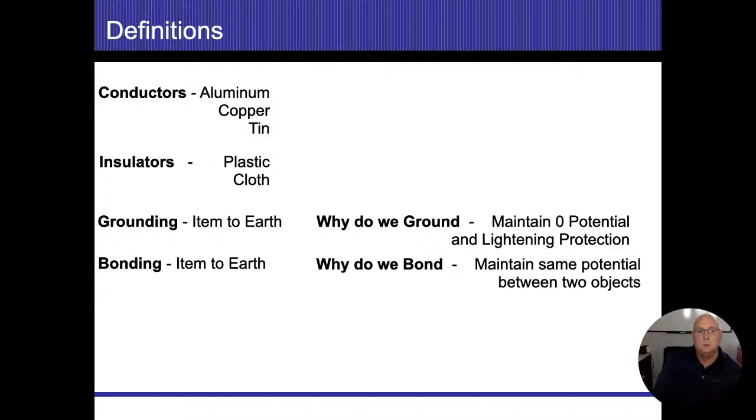Aluminum in residential wiring was used around the mid-60s to the mid-70s. If you don't know that already, you are going to want to write that down. So again, it's the mid-60s to the mid-70s. It's going to have plastic insulation, and single strand wiring really isn't allowed anymore.